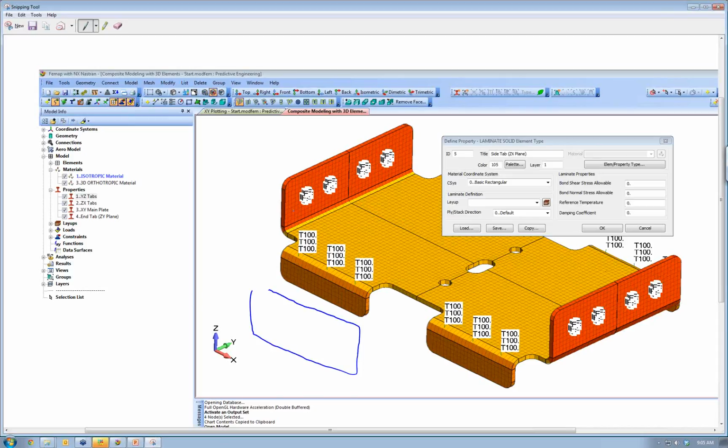And we talked about our fiber alignment for maybe our bottom ply. We wanted it in the global Y. But as this tab is wrapped around here, our fiber direction is going to wrap around and be in the Z direction. And that way it's going to be continuous with these other sections as we set them up.